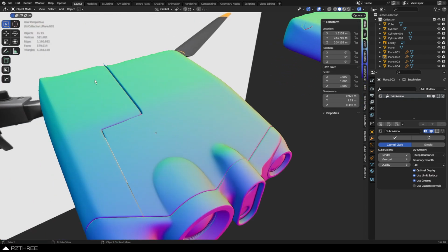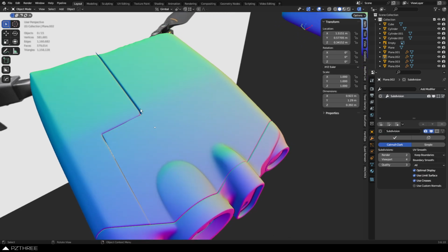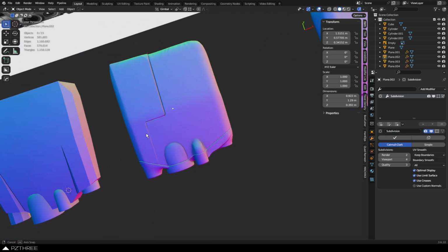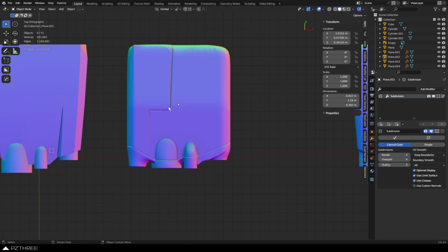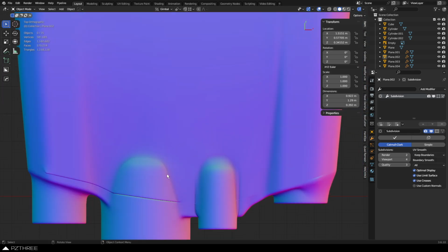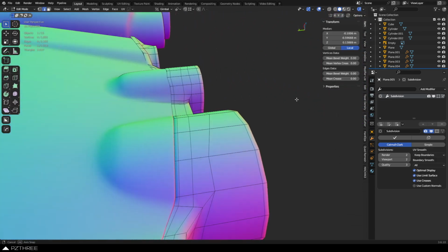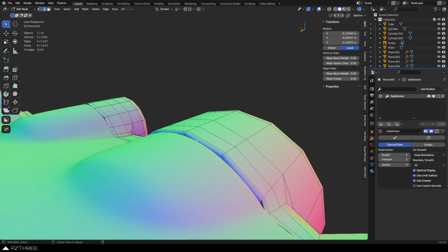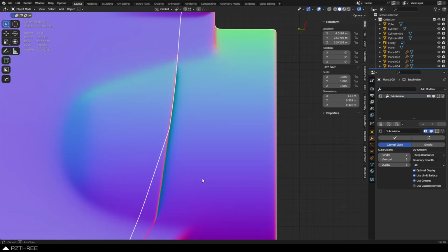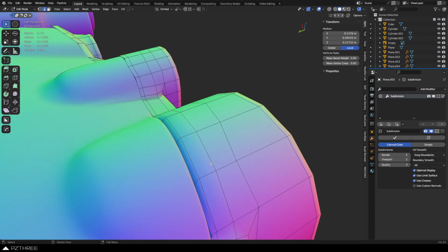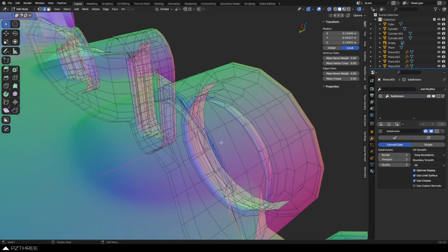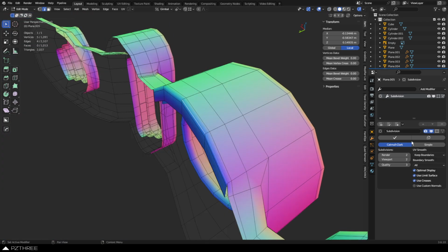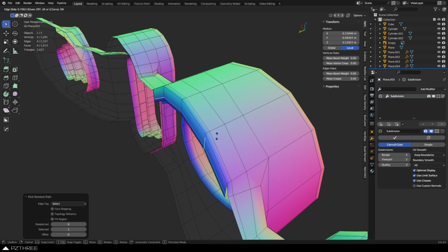So, match these things up so there's no gaps. But if you make your normals a little bit more pronounced like this, it's going to look much better in a video game than it would with something like this. And so, even just creating more rounded bevels could potentially help out here on something like this. Even if you've got to dissolve an edge and do something like that. I mean, maybe that's a possibility. But in our case here, I feel like just backing these up would probably be our better bet. So it's just a much bigger bevel.